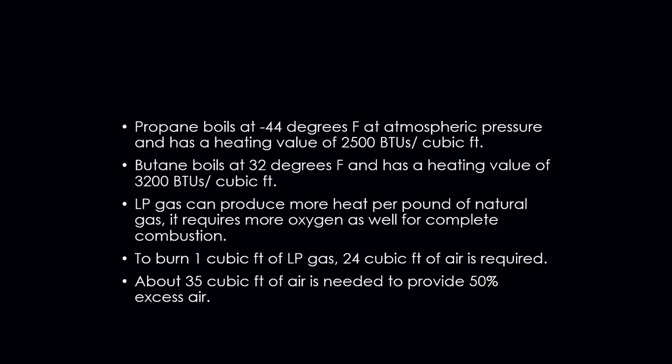for complete combustion. You need to understand the difference, the specific gravity of each one of these different gases in order to truly understand how it's going to burn. The heavier the gas, the more air you're going to need to support complete combustion. To burn 1 cubic foot of LP gas, you need roughly 24 cubic feet of air in order for it to occur.